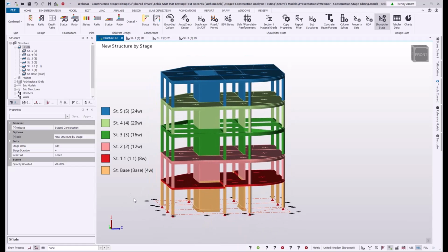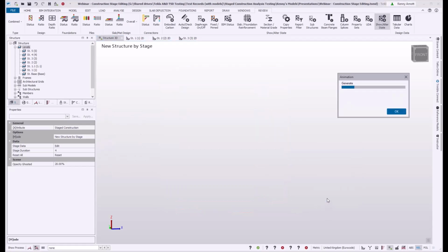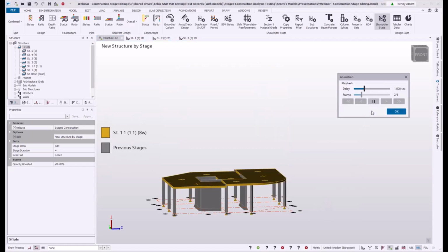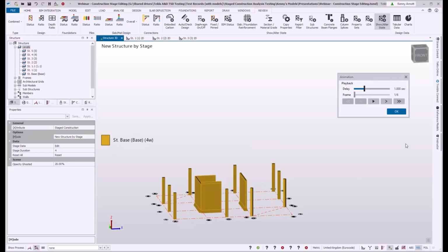And so this is a level of detail which you could do, but I think in terms of structural analysis, it doesn't really add to anything. And in fact, as I'll demonstrate here, it causes a problem. So I've now got a stage 1. If I go to my animate view, that's all that exists, and these columns are on pin bases.